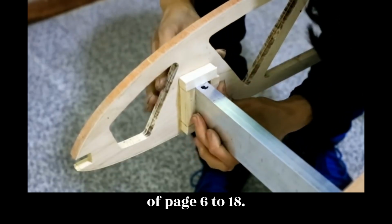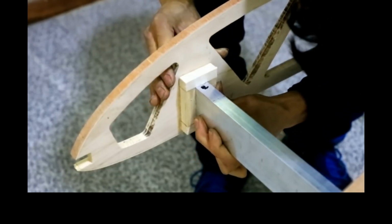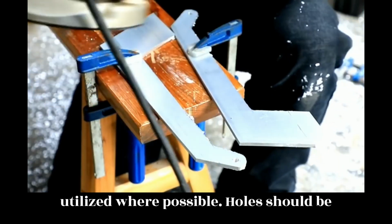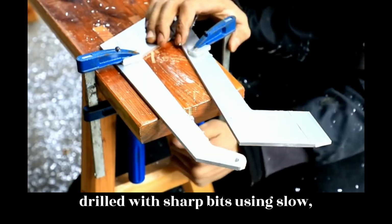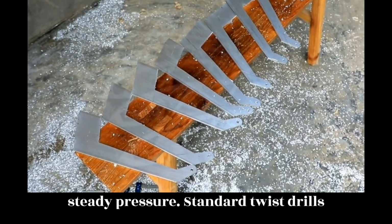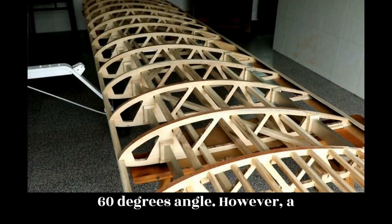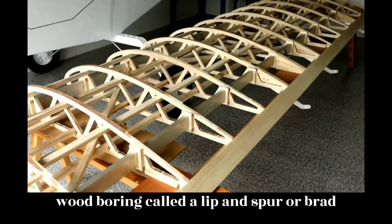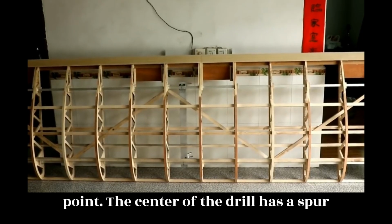End of page 6-18. For boring accurate smooth holes, it is recommended that a drill press be utilized where possible. Holes should be drilled with sharp bits using slow steady pressure. Standard twist drills can be used in wood when sharpened to a 60 degree angle. However, a better designed drill was developed for wood boring called a lip and spur or brad point.